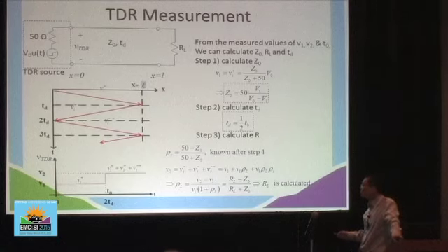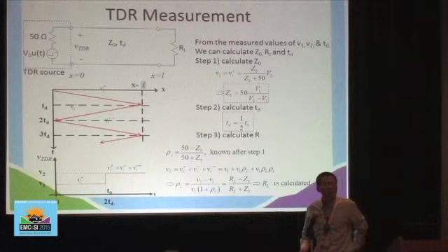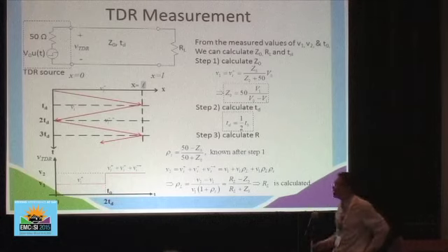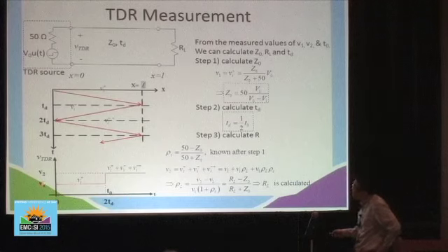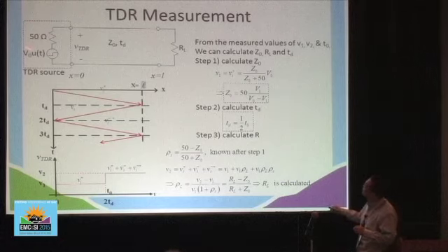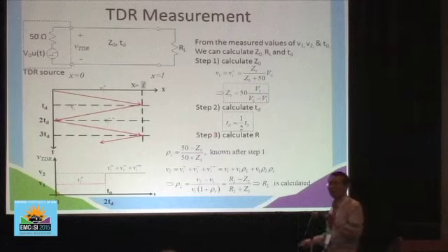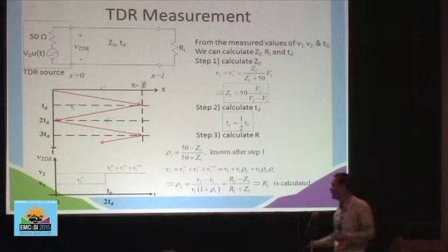And these two voltages and the time information give us critical information about the transmission line. Okay, first of all, this initial voltage, between t equals 0 and this time, is the initial right-going wave. This initial right-going wave, as we said, is a ratio of 50 ohm and Z0. So from voltage 1, we can get the characteristic impedance of the transmission line, okay?